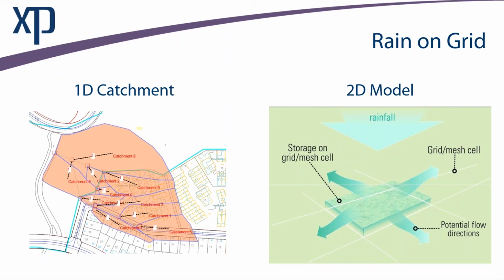So instead of using a runoff model that collects things at a node, we're going to let the flow fall directly on the cell, and then the rate of rainfall and the elevation of the cells adjacent to the cell in consideration are going to be computed. That's going to determine which direction the flow goes, which adjacent cell is going to receive the flow. That's a much more accurate representation, again, of what happens when rain actually falls on the ground.